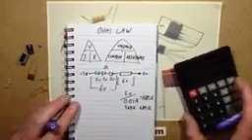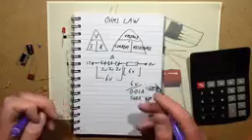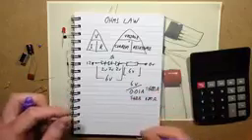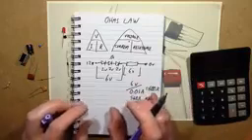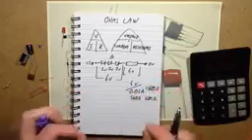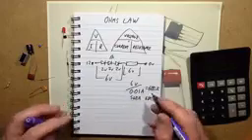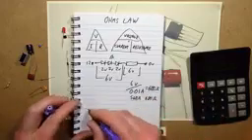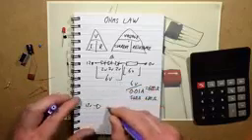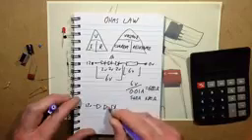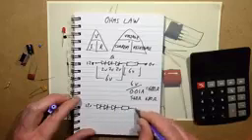And the other way this formula can be used is if you are trying to measure how much current's flowing through some existing LEDs, say for instance you're measuring some LED tape. Putting an ammeter in series with it actually skews the reading a bit, because the voltage drop across the resistor in series with the LEDs is so low. So say for instance you've got a 12 volt supply and it's feeding more LEDs, but you don't know the voltage across the LEDs and you don't know the current through them, but there's a resistor and you do know the value of the resistor.